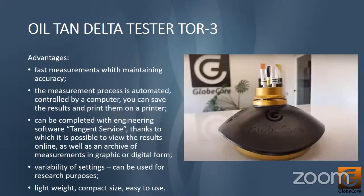Having a TOR3 in your laboratory's inventory allows you to address two problems at once: to determine if new oil is suitable for filling transformers and how long existing oil can be used without change or regeneration. This increases the reliability of transformer operation and prevents emergencies associated with malfunctions of the insulation system.